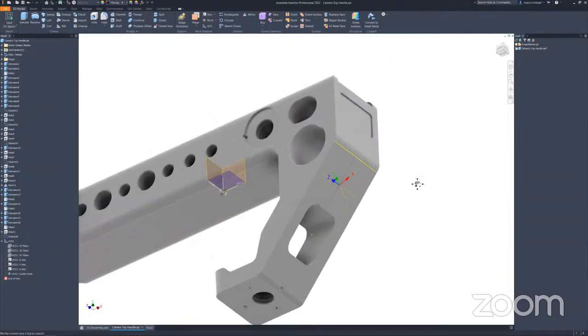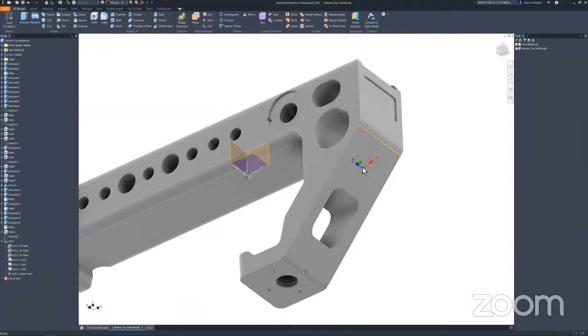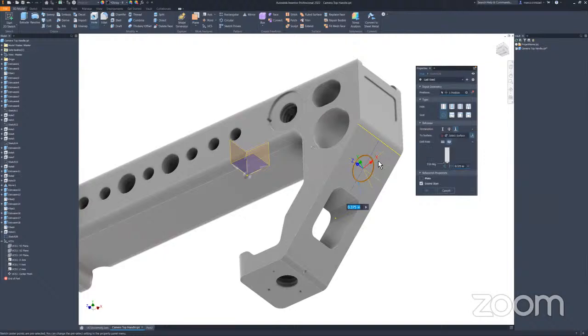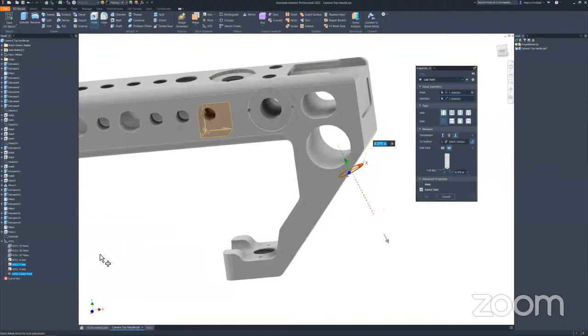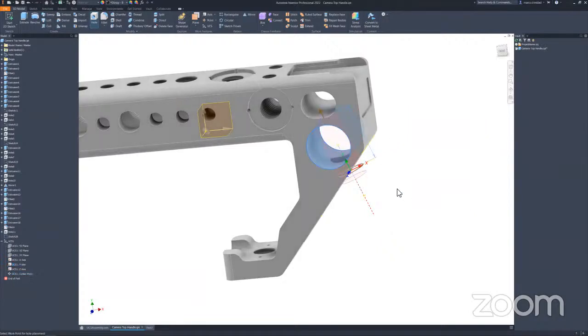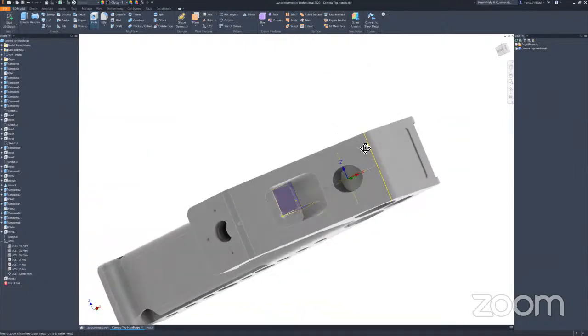Yeah, looks good. And like you said, I know I kind of placed it haphazardly, but if I were to add some dimensions here, I could move this, and then it would move the feature that I would add. So I can go in here and close out of this bump feature. I can go here, select that point on the UCS, and then select the direction, which I want to be the Y direction. Oh, look at that. And then place that. And then I want to go up to surface, which will be the surface. And there's my whole feature.